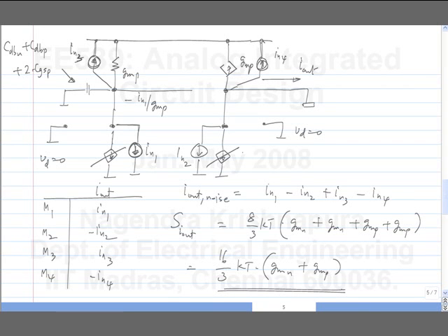Okay, that is something inconsistent. I have not taken off any marks for it, but that's clearly not correct, right? You either do it at DC and say that my answer is valid for DC, or you do it for all frequencies. You can't take the current output at DC and divide it by the transfer function over all frequencies and say that's the spectral density over frequency. Okay.